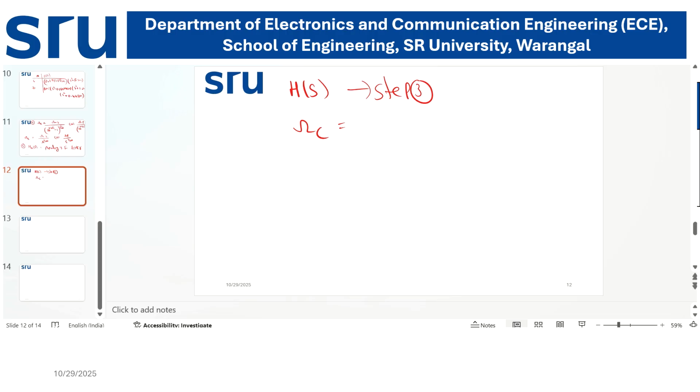Suppose you find the cutoff frequency using the passband frequency and passband attenuation and you get 12.44 radians per second. And if you find it using the stop band attenuation and stop band frequency, suppose it is 8.944. In between these two the highest value is 12.44, so the highest omega, that is the cutoff frequency, you have to consider as 12.44 radians per second.